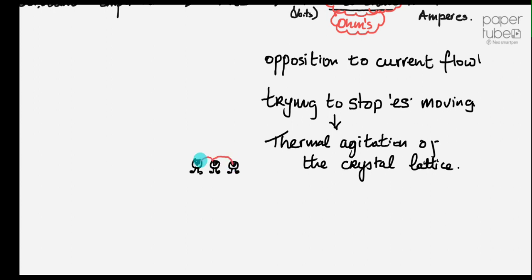Well, if you're a flea jumping from dog to dog, and these dogs are moving, see how I went into the third colour there? I suppose you're impressed. If they are moving, the flea would find it more difficult to jump. So the analogy is the electron would find it more difficult to move because it'd be impeded. So therefore, if you increase the temperature, less electrons move and the resistance increases. Fair enough?